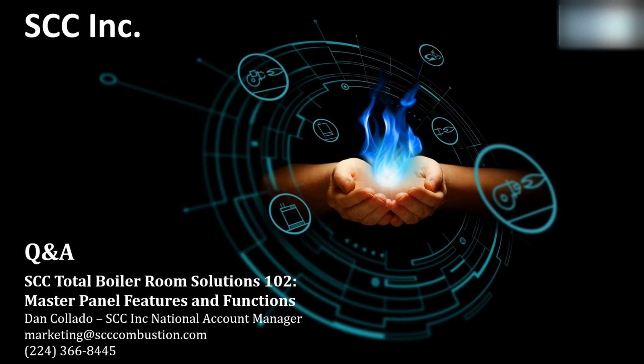In the case of a hot water boiler where the master panel is controlling the primary pumps or the isolation valve at the boiler, the associated relay contacts that are actually located in the master panel will fail closed so that the pump or isolation valve will run or remain open. This also ensures that the master panel doesn't affect the ability to operate hot water boilers locally. So, good question for sure. Let's see if we can grab a few more of these.